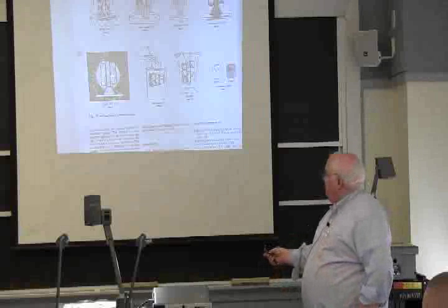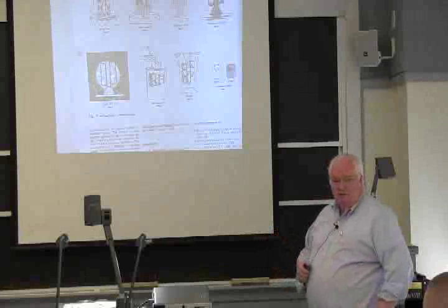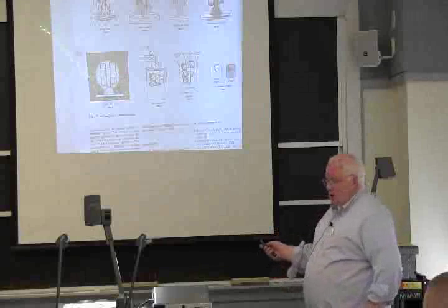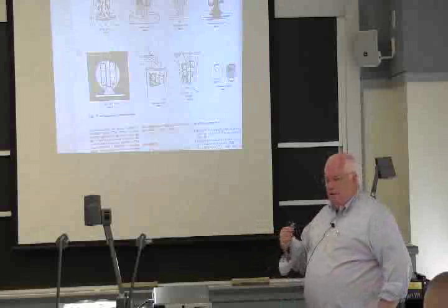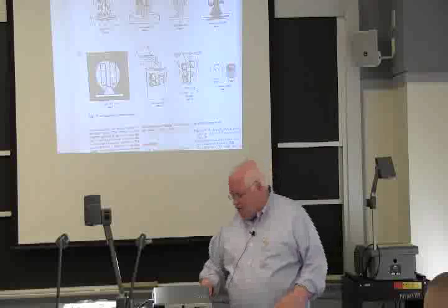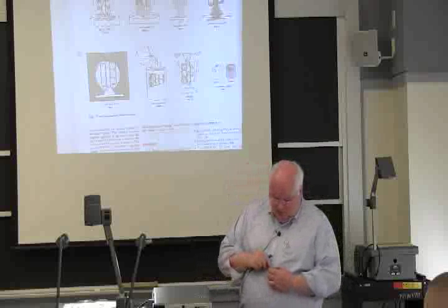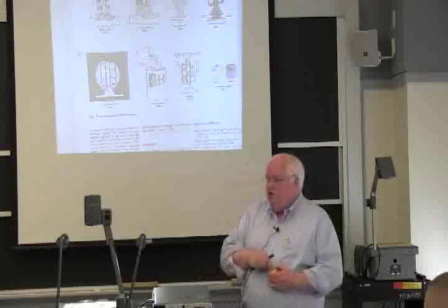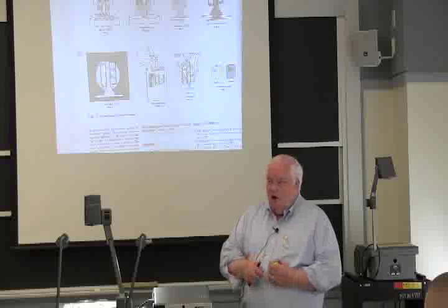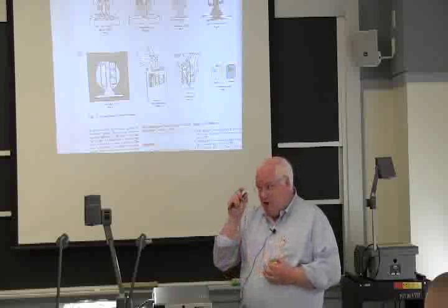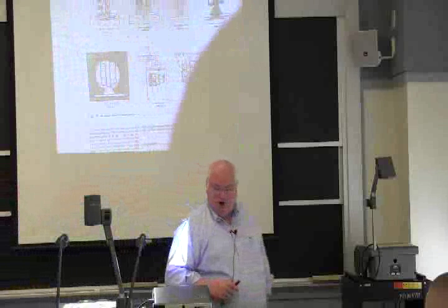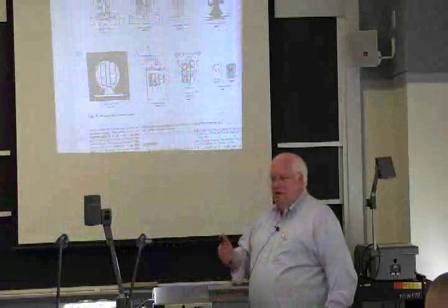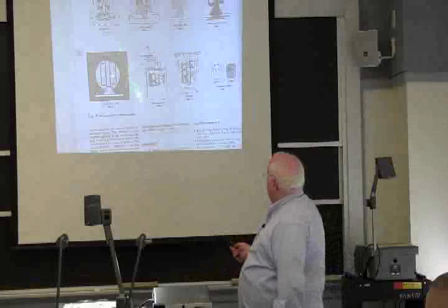This might be a 2000 degree furnace, 2000 F, okay? Because this is all ceramic now, and you're going to bond this stuff together. But the first layer was this very fine flour, and the reason I wanted to bring my latest brass rat, you can read Massachusetts Institute of Technology across here. But even the one that fits on my hand, if you take a magnifier, you can read the Massachusetts, all the letters of MIT going across there on my actual brass rat. If you use a fine enough flour, okay, you can get very, very good detail in your part.